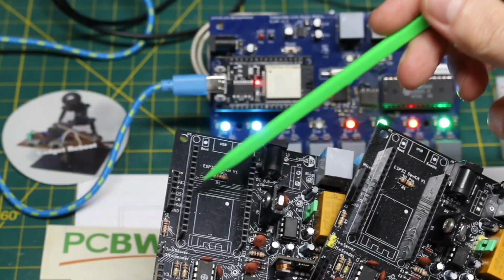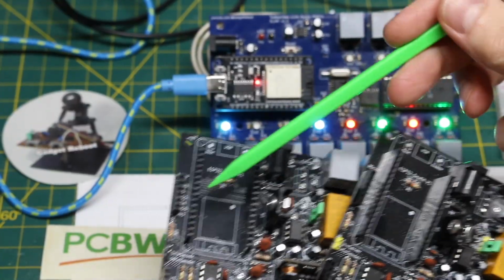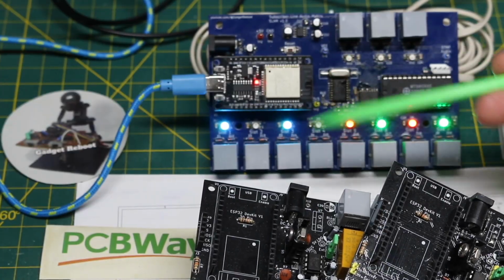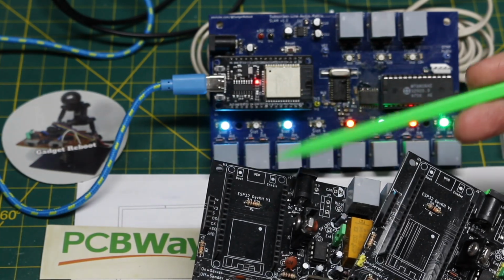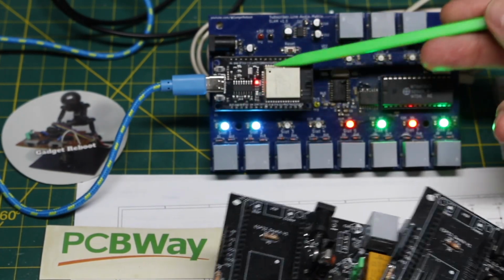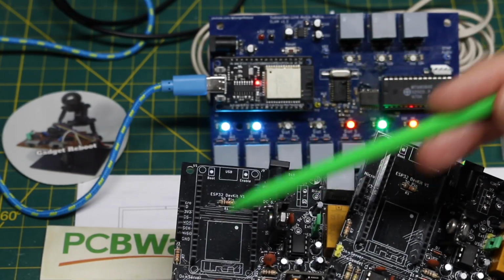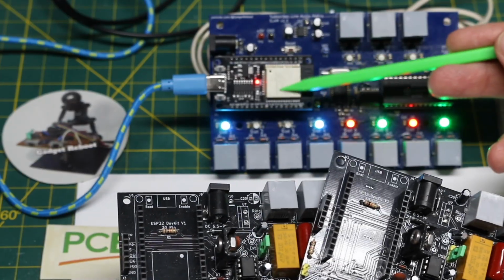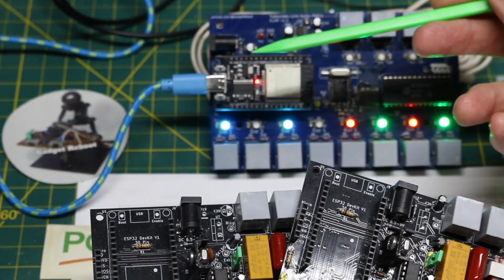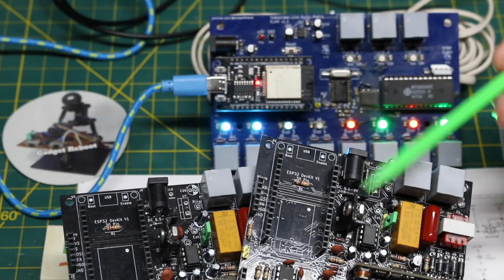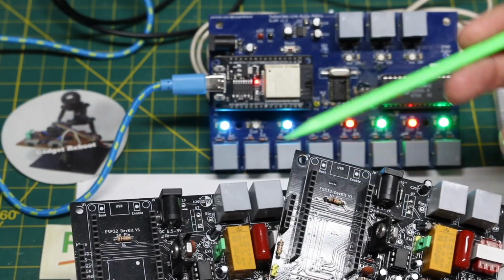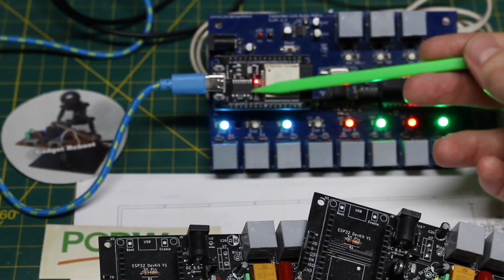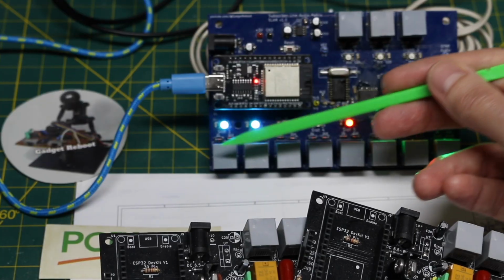When a phone dials from here to here, instead of directly wirelessly communicating to coordinate the call, the system is not ready functionally yet with software, but now each node will talk to the ESP on this matrix. So this board would tell this board wirelessly, I'd like to call the number associated with this board. Then this module will ask this one, are you available for a call? And if so, now with each one having a landline connection up to the matrix, this ESP will route the call from one node to another.